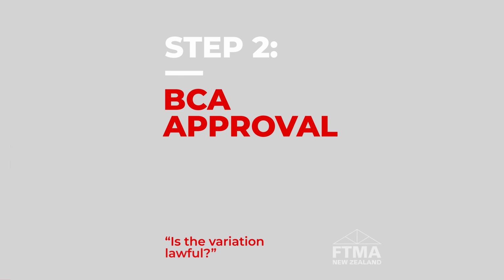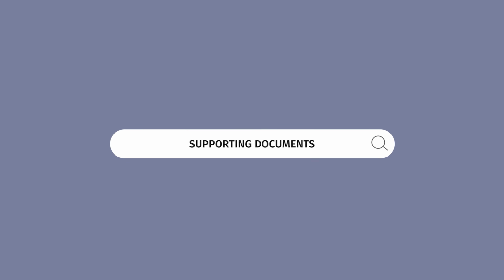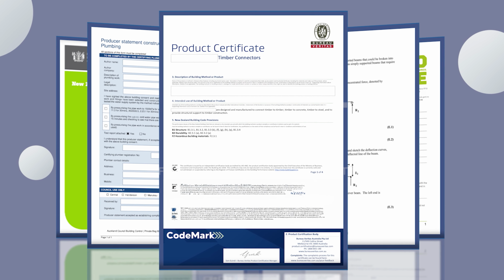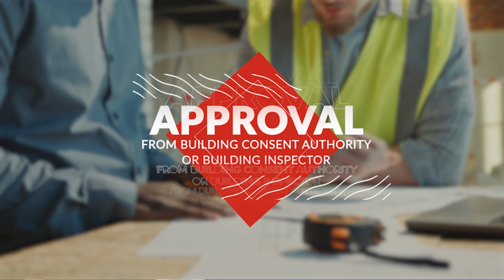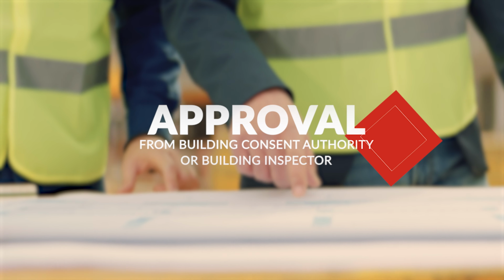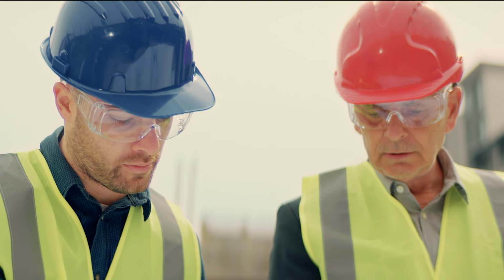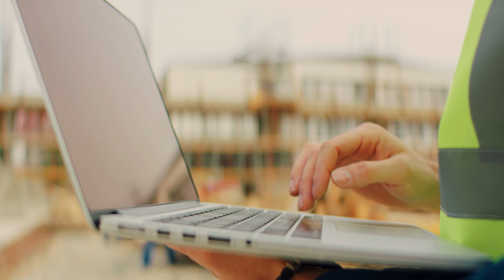Step 2. BCA approval. If the alteration falls within the definition of a minor variation, the task is often to provide supporting documentation and obtain approval from the building inspector or the building consent authority before the product substitution is installed. In some cases, for very simple minor variations, they may be able to be approved on site by the building inspector, who will make an official note of the variation on their inspection documents.